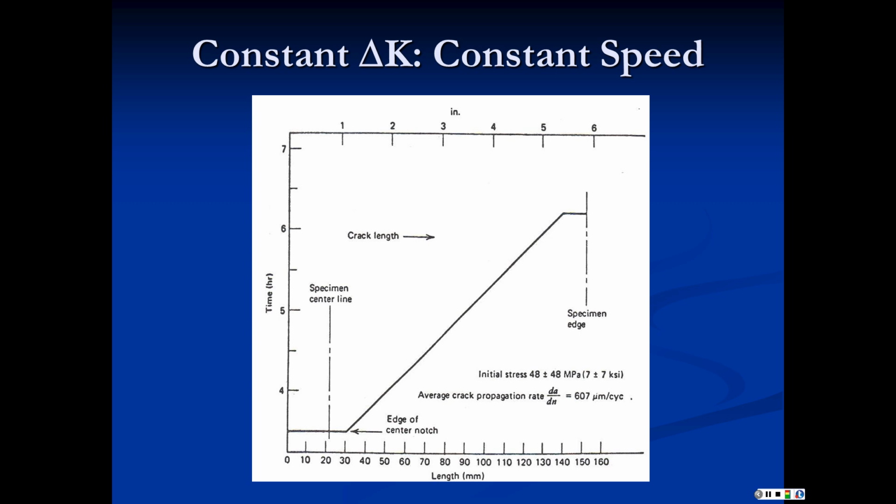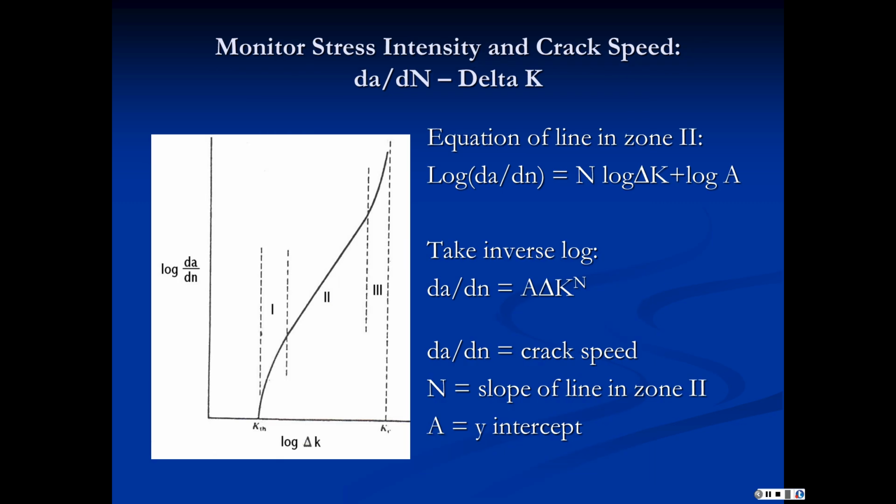All right, well, that's promising. That means that there's something fundamental. It doesn't matter how long the crack is, it will grow at the same speed as long as the delta K is the same. So it's delta K that drives the velocity.